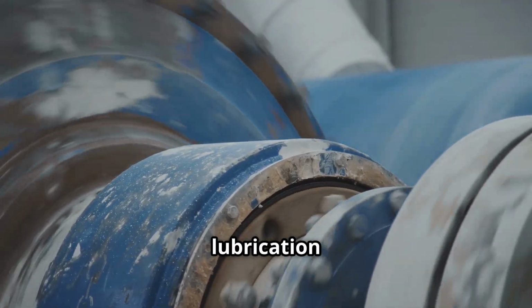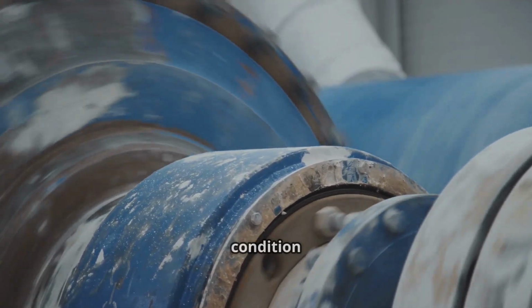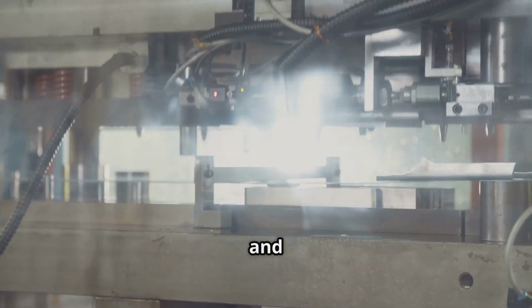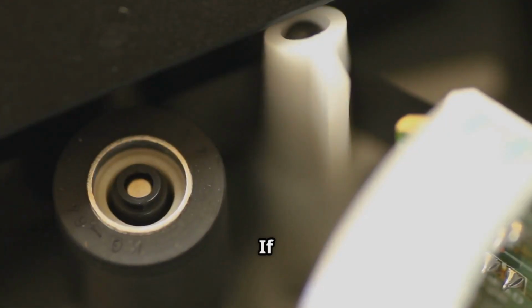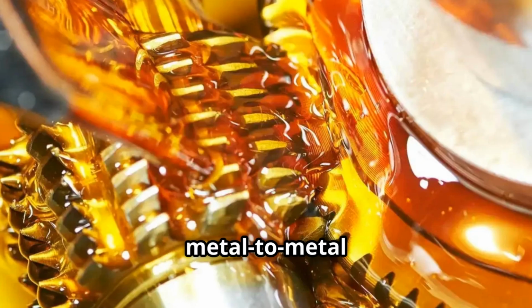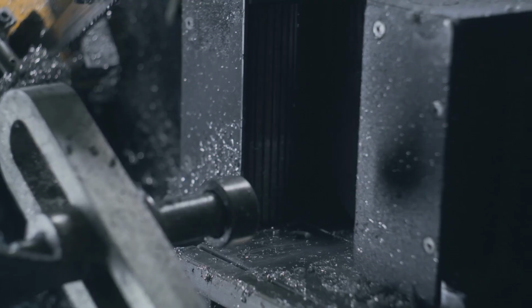For hydrodynamic lubrication to be effective, the oil's viscosity must be such that the hydrodynamic condition will be maintained under every operating condition, such as high speed and high load, low speed and high load, low speed and low load, etc. If the operating conditions cause the working clearance to be reduced too much, metal-to-metal contact between the metal high spots or asperities could occur.